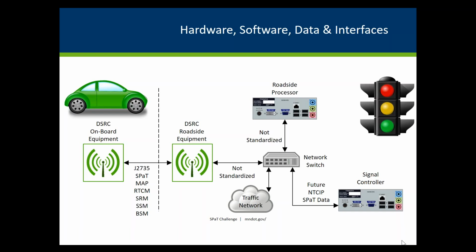Let's see, I think the only other thing I wanted to mention, this shows a traffic network. A lot of our signals are tied back on a network to our central, and now if we're going to hang things that look kind of like Wi-Fi out on these, all out in the public, there's going to have to be some serious consideration given to network security. You know, we don't want to open our whole traffic network up to everybody who goes by.